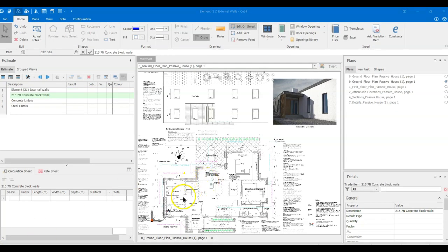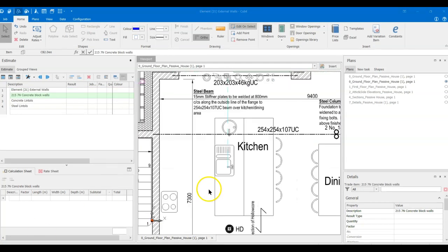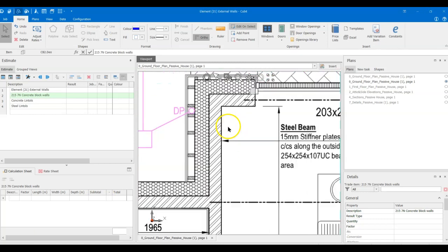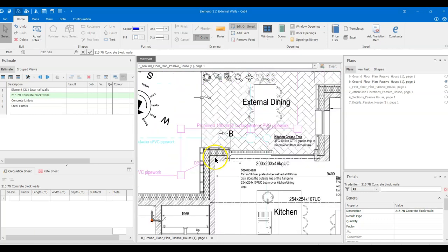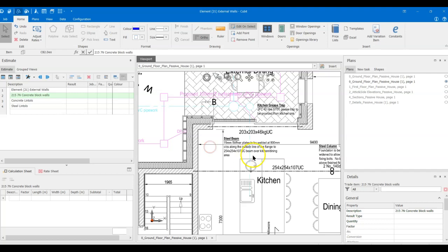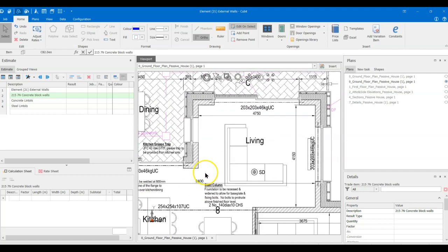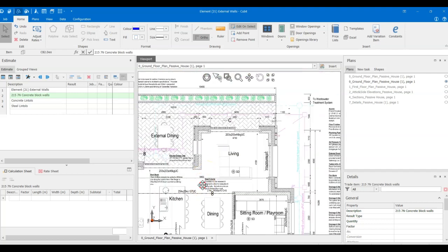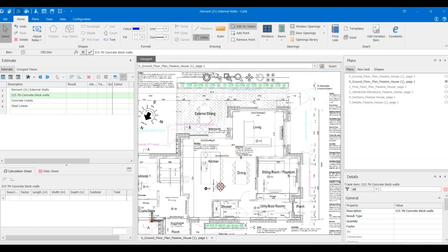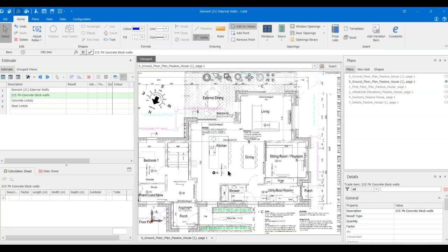Okay, so we've had a little look at our drawing, and essentially because our drawing is a single leaf, we have external insulation, which is our wall finish, which will be measured separately. We don't have any of those labours that were listed out in Tony's take-off sheet. So we essentially have block walls, concrete lintels, steel lintels, 3 items to measure. That's it.